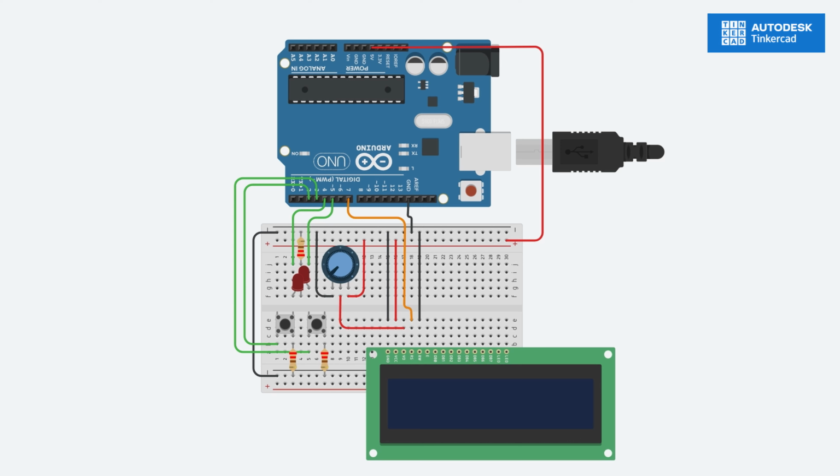We simply connected it to ground since that is 0 and that is the writing mode, and since we will only be writing on the LCD display, that's the only thing we need. After that, we'll connect E on the LCD display. That's the enable, and this is also just to instruct the LCD on how to write things.